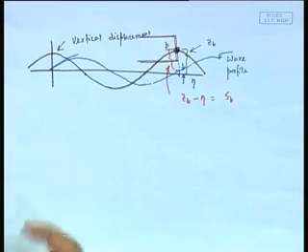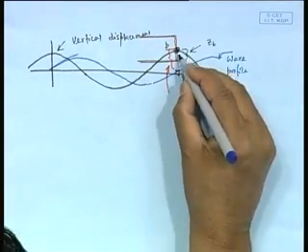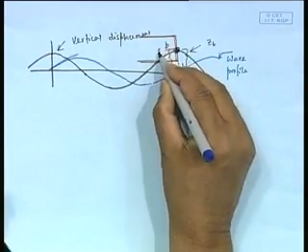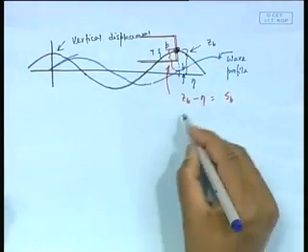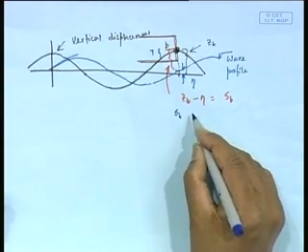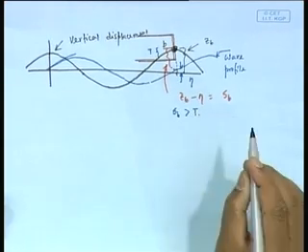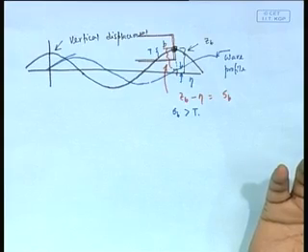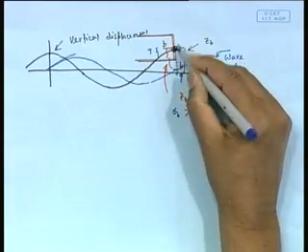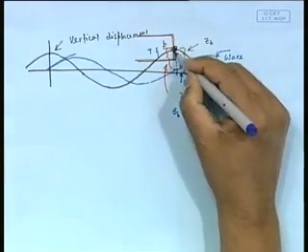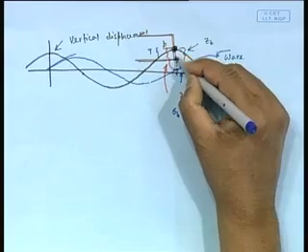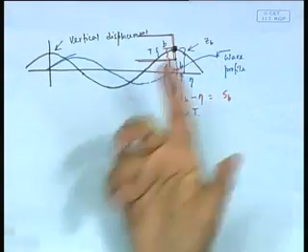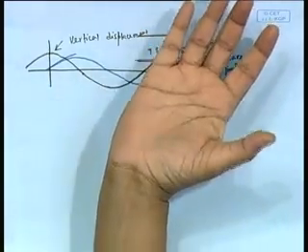Now obviously you can make out from here that if this is T, the draft here, and SB is more than T, what happened? The forefoot has come out, the bottom would have come out, isn't it? SB is this much and T is this much. So obviously if SB is more than T, my bottom has come out of water.